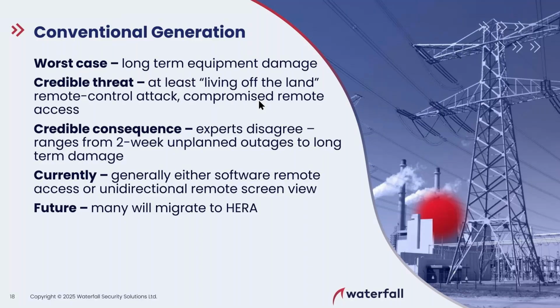Today, practically speaking, what we see in conventional power plants, we're talking coal or natural gas power plants, we see either software remote access or unidirectional remote screen view. That's what we see today. Hera, hardware enforced remote access, screen images out, keystrokes in, hardware filtering, that is newer, and we don't see it widely deployed yet, but we do see a lot of power plants looking hard at it because they want something stronger than software. Even if they're not willing to give up remote access entirely, they want something stronger than software.